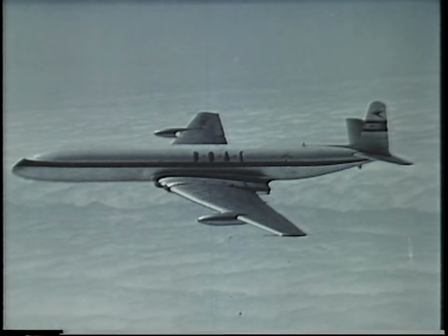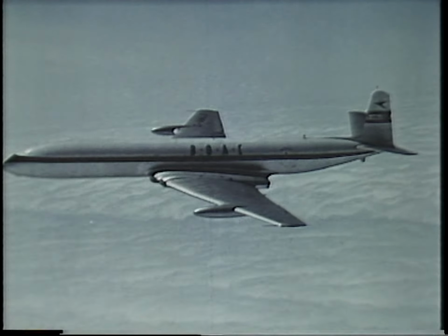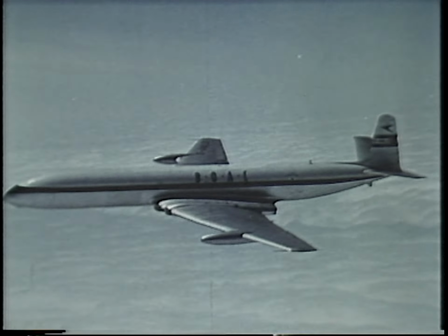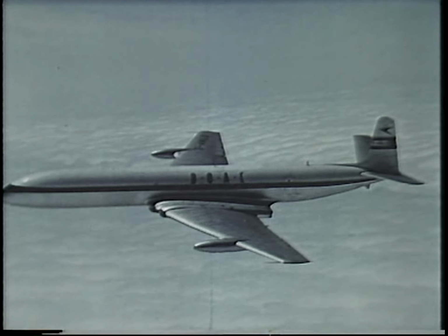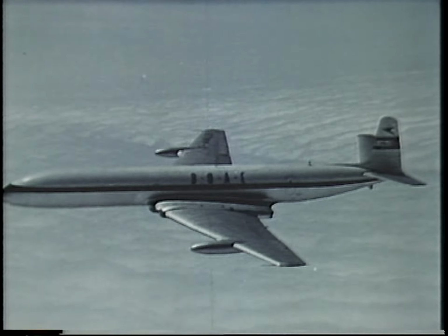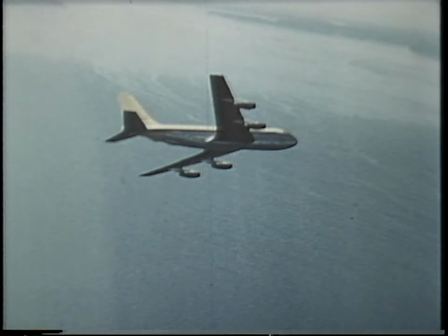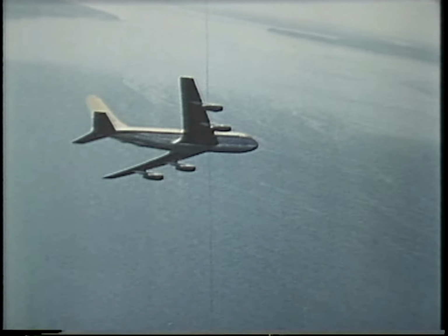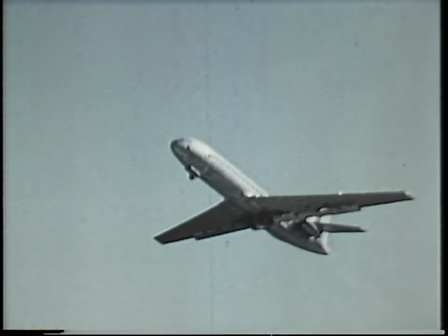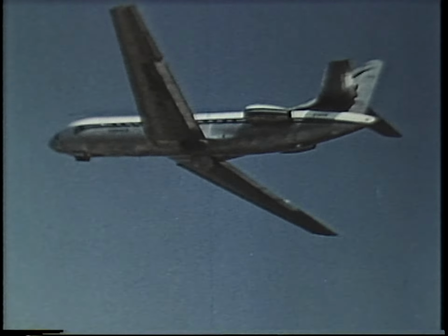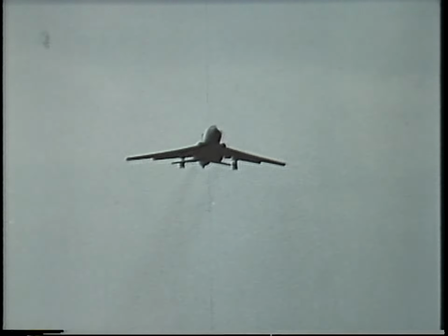High-speed airliners of today use thin wings and sweep back to obtain high critical Mach numbers. By cruising at high speeds, but still below the critical Mach number, they avoid shock waves altogether and the troubles that come with them. But wings can't be made too thin or too highly swept back, or low-speed flight and landing would suffer.